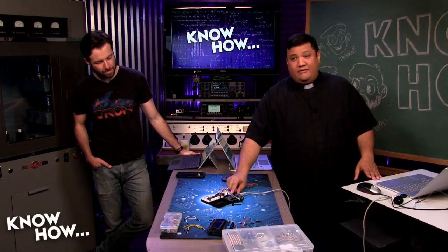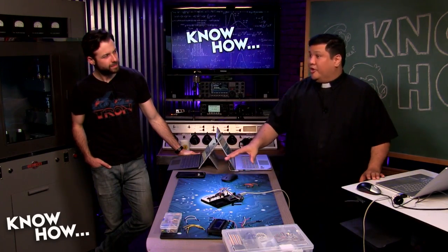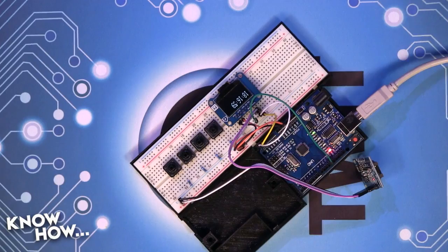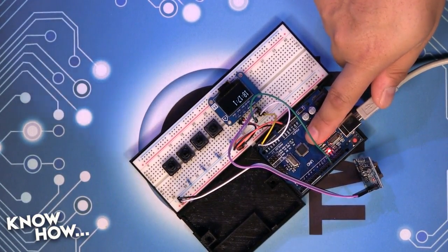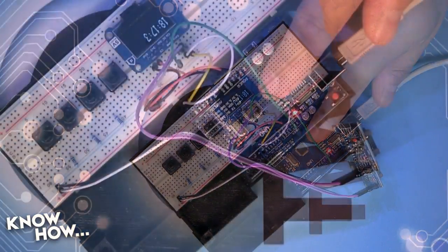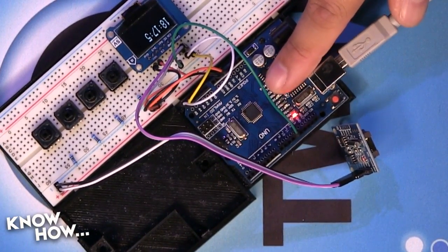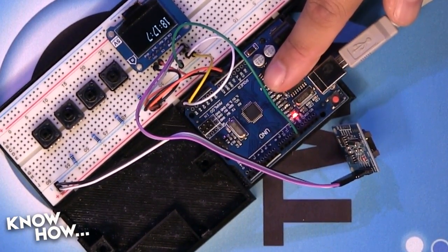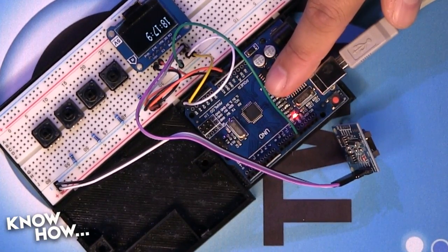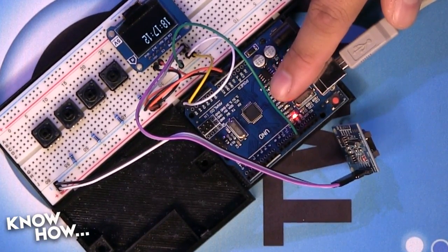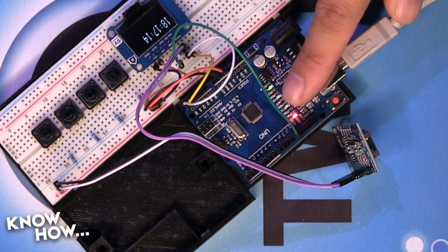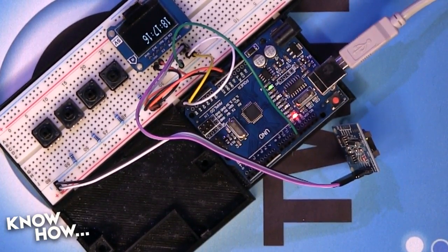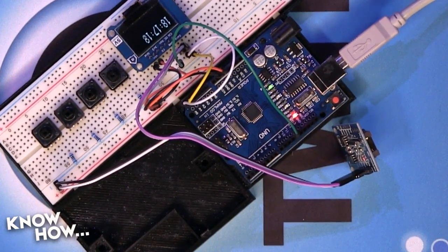So what we have are three different types of memory on any Arduino that's based on the ATmega. This is the 328. It's got 32K of flash, so I can store 32 kilobytes, bytes, not bits, kilobytes worth of program. I've got 2K of system memory, and I've got 1K, so that's 1,024 bytes of EEPROM.